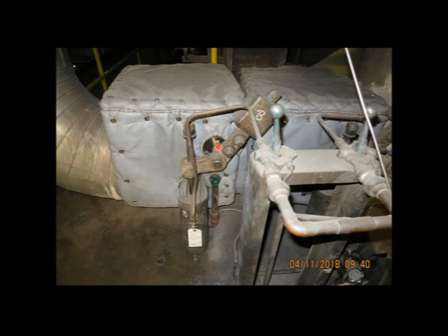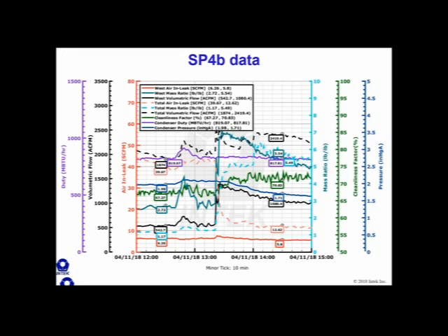They replaced it with a valve stem that did not require a steam seal packing gland, but they didn't plug up the drain here. This drain goes around to the other side of the condenser and goes into the shell wall as one of the drains entering that wall. And so this was abandoned. There was a large leak coming in here. We found that with the helium leak detector. We were able to plug it.